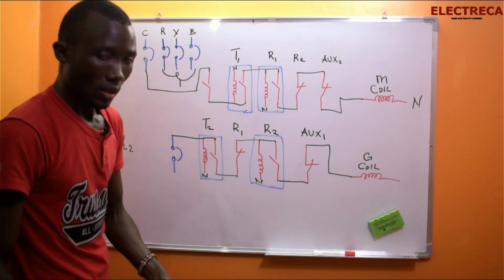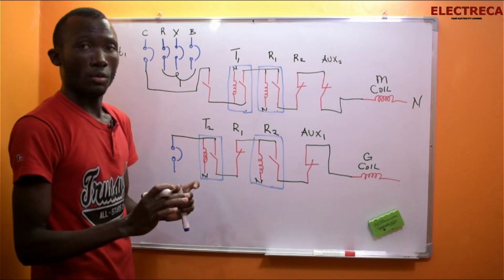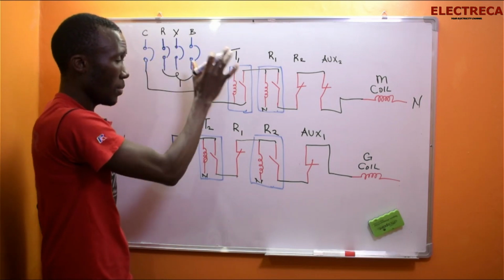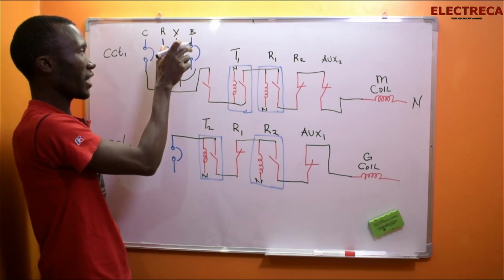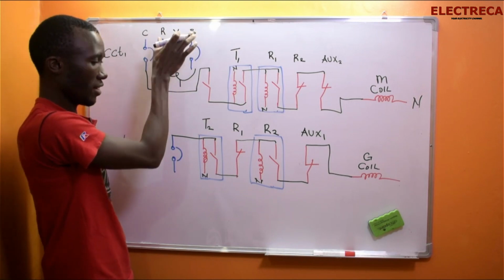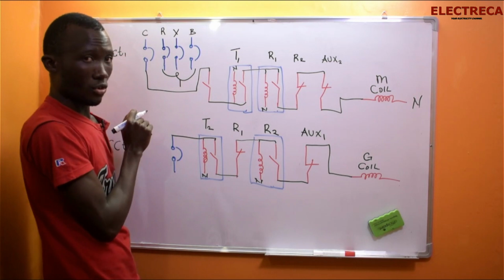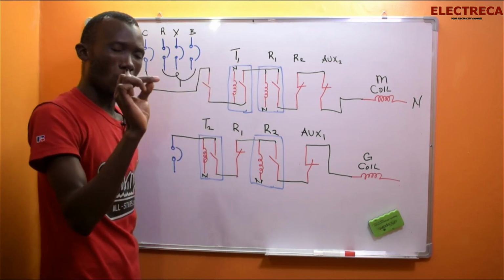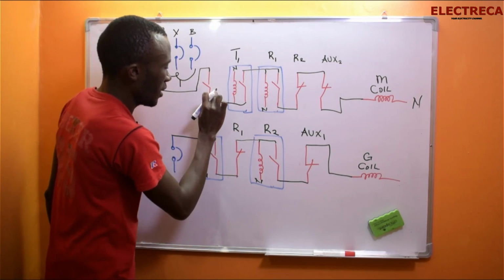All right, now let me explain. Now, this is our main. Now you see that from the control breaker, these are 4 breakers. The 3 breakers are carrying the 3 phase, controlling the 3 phase that is entering the monitor relay, and then this is a control breaker. So our current moves through the normally open of the monitor relay, okay? You see, through the normally open.